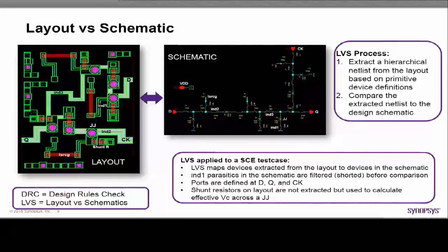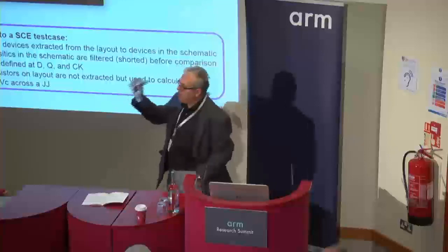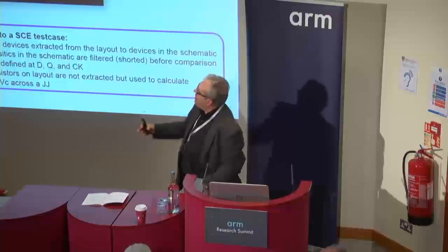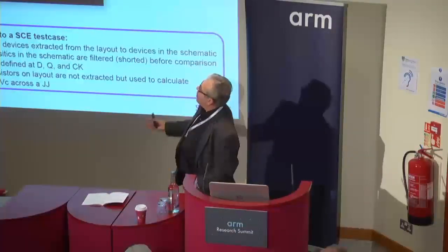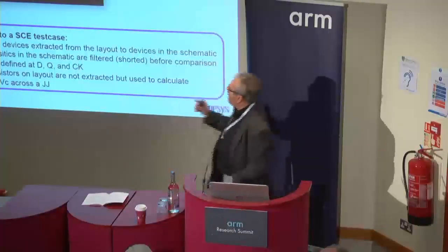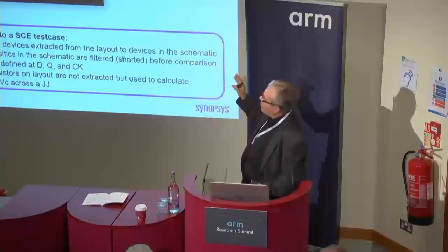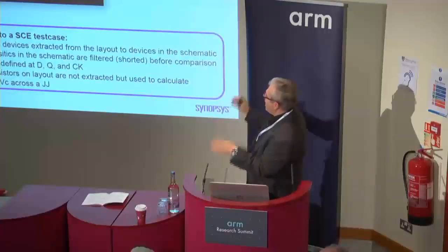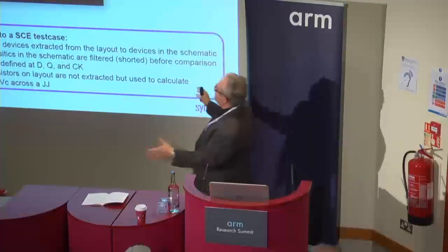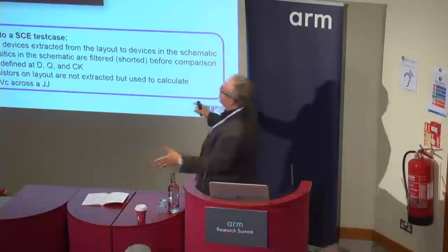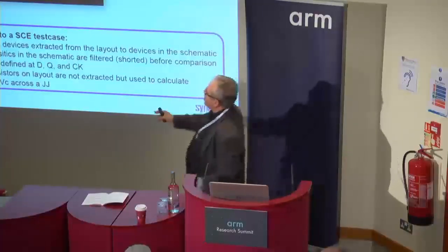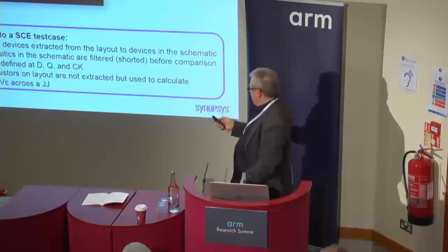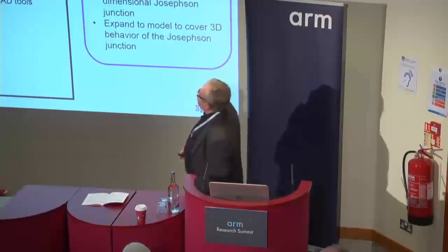This is a far more mature way of looking at it than doing one cell at a time and then waiting until the whole chip is placed and routed, extracting it, back annotating it, only to find out that, oops, let's go to the beginning. That's a lot of time wasted. So what we stress in our methodology is that within a front-end tool, and here I try to be as technology neutral as possible, not to make the presentation an advertisement for Synopsys or anything, a mature tool has to invoke all those things from the same tool. And this is what we are targeting in this superconducting program.